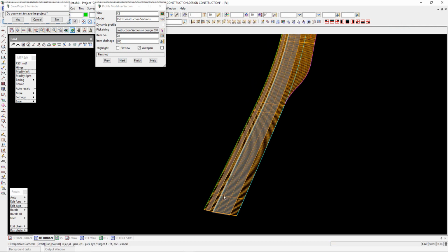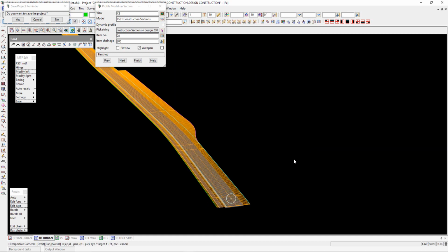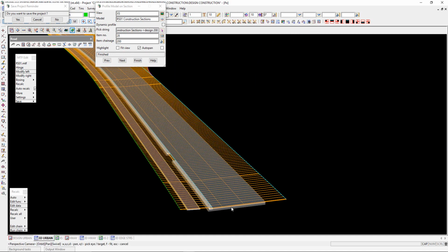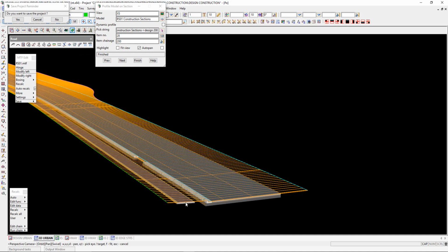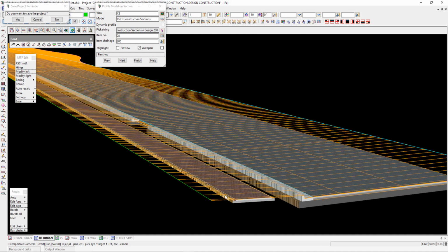So we're looking at our footpath profile and our road surface. Again, checks are done in relation to the existence of strings. You can actually just go from start to end, and it will only produce the pavement or the profile for the footpath where either of these two strings exist. So a lot of the errors are taken care of for you.